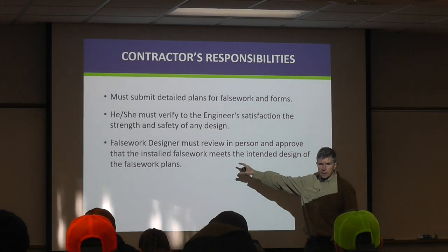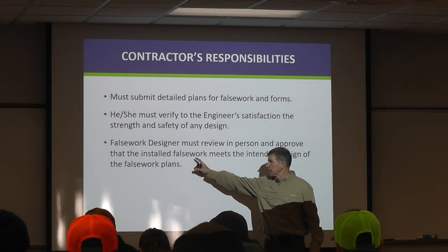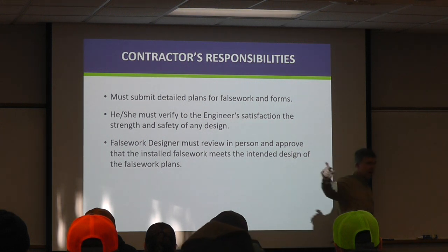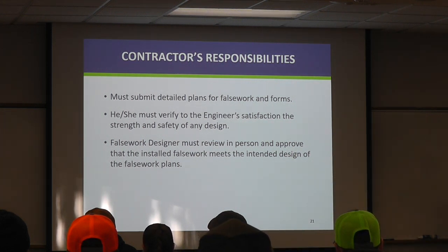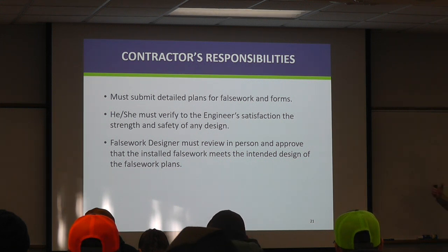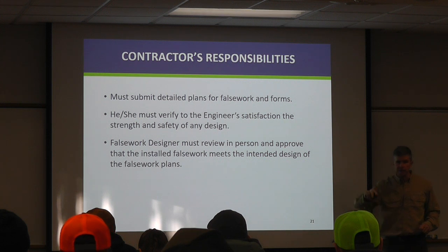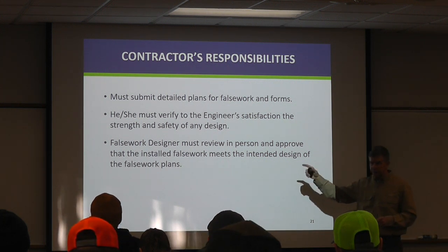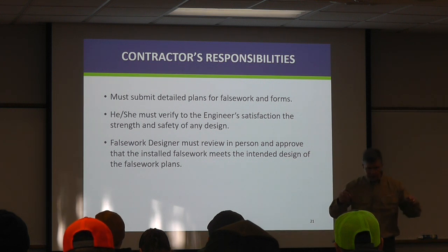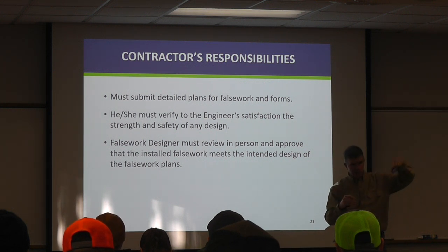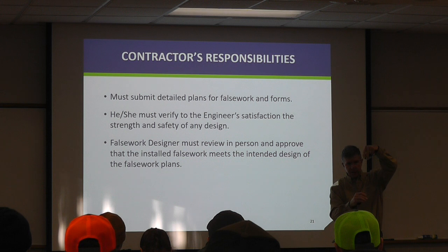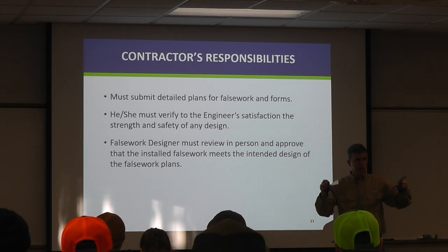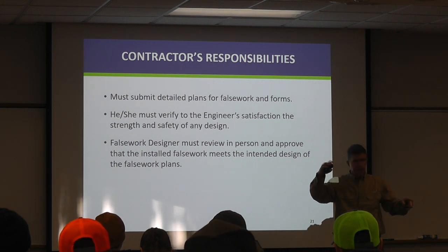After that incident, MnDOT toughened our specs, and we require the falsework designer to come on site. Like on St. Croix, the falsework designer was out there probably 8 or 10 or maybe even 12 times at all the different spots of falsework. And the reason the Lake Street collapsed is there was a bunch of little members coming in, load transferring down, but everything came down through a 36-inch deep beam.